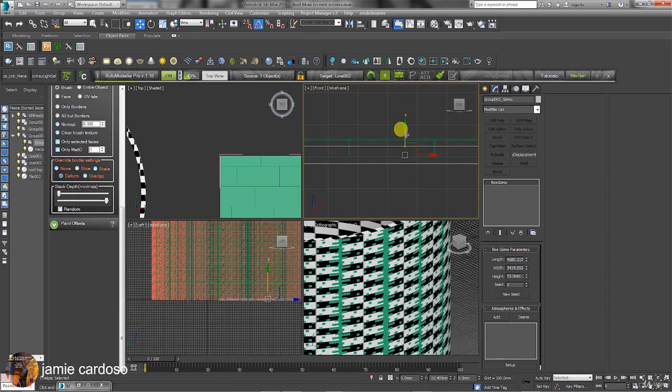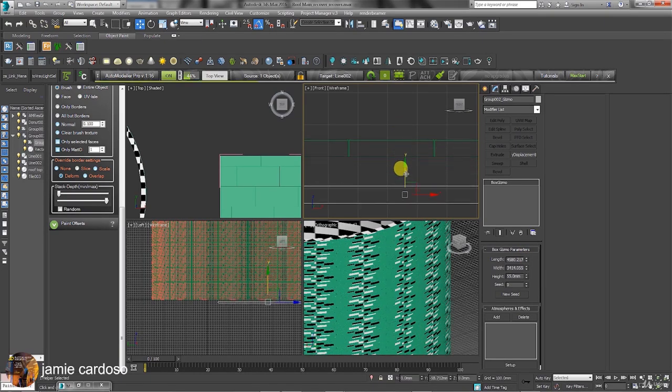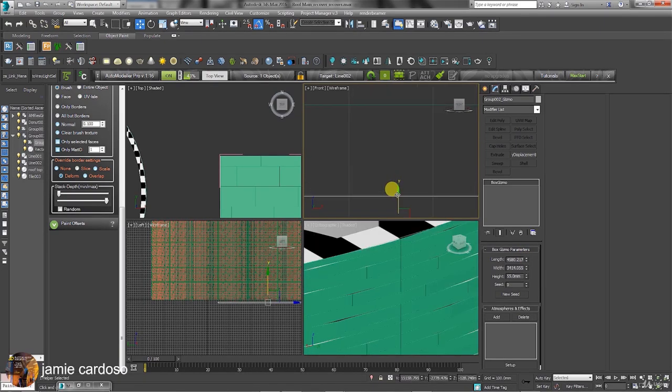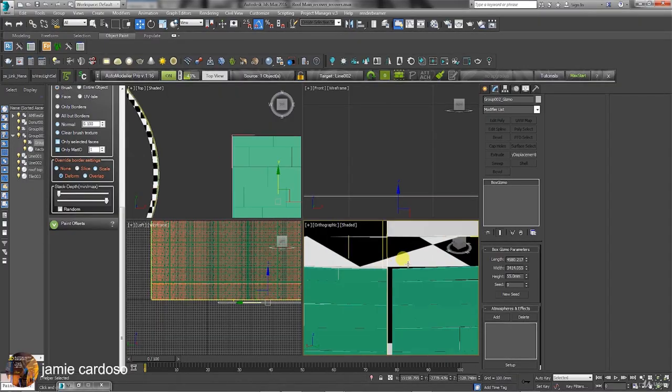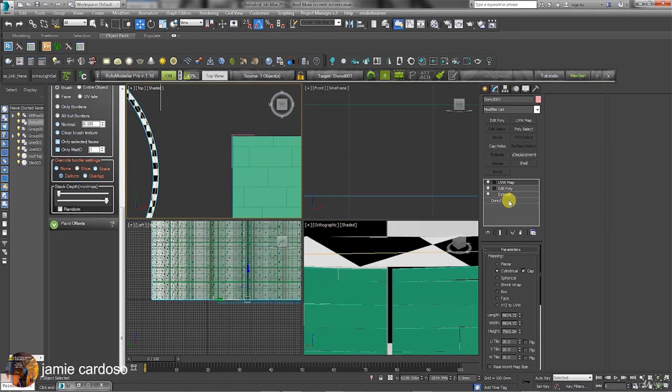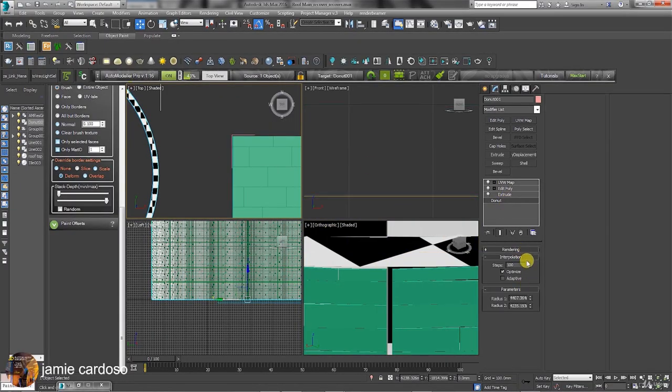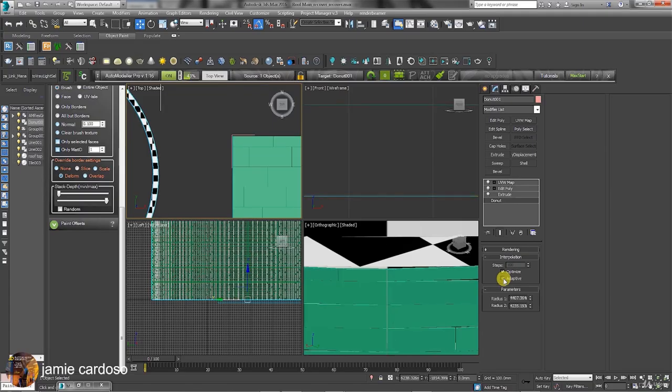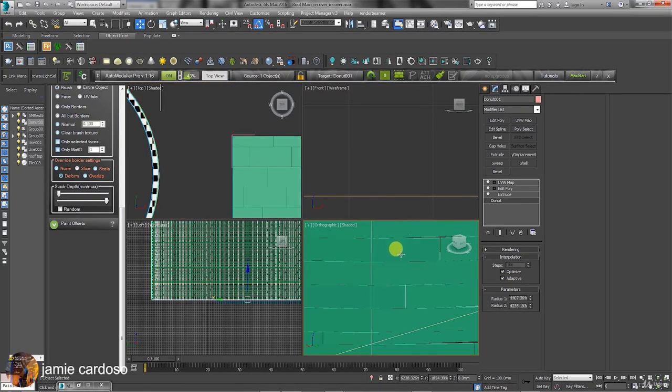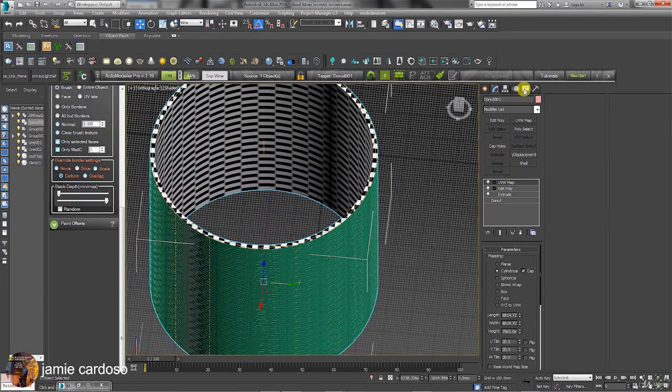As previously done, let's adjust the gizmo of the mesh source to ensure the tiles are not sunk into the cylinder. To overlap this gap, let's select the cylinder object and make its step values adaptive. As mentioned earlier, the smoother the surface, the more accurately the painted mesh will deform to it. Let's hide the cylinder to see the curved tiles.